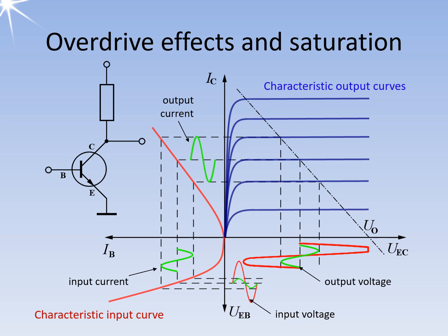There are many of these amplifiers in radar receivers. The effect of saturation is exacerbated because the input signals have a dynamic range of usually more than 40 decibels. The radar has to see very weak echo signals from ultralight aircraft and at the same time deliver an undistorted signal from very large fixed targets to the radar signal processor. A simple selection of well-designed bias voltages cannot control this dynamic range.